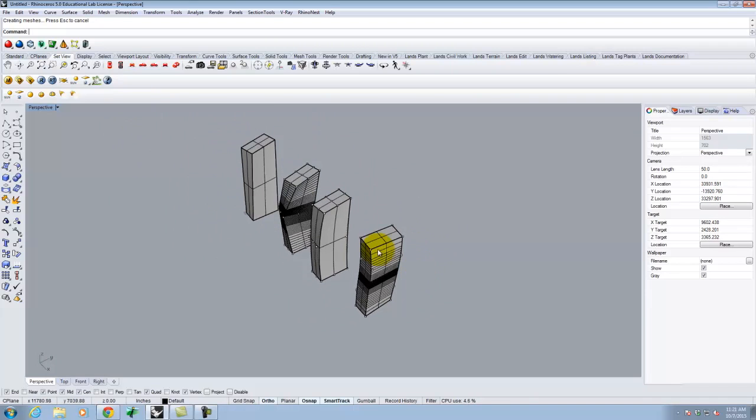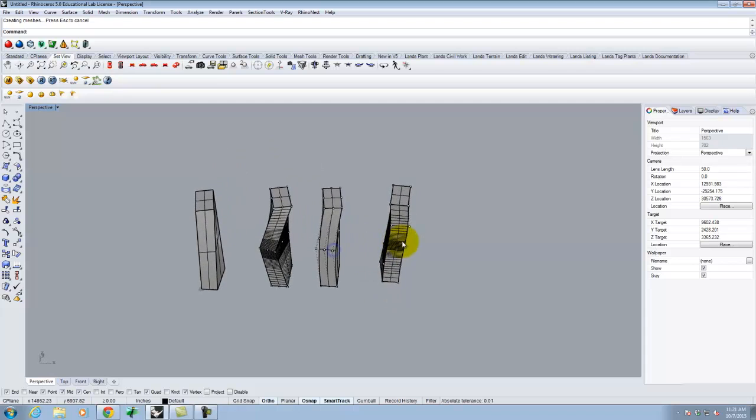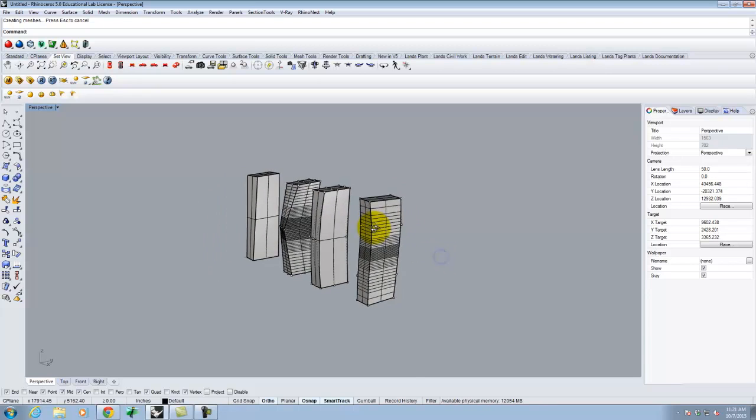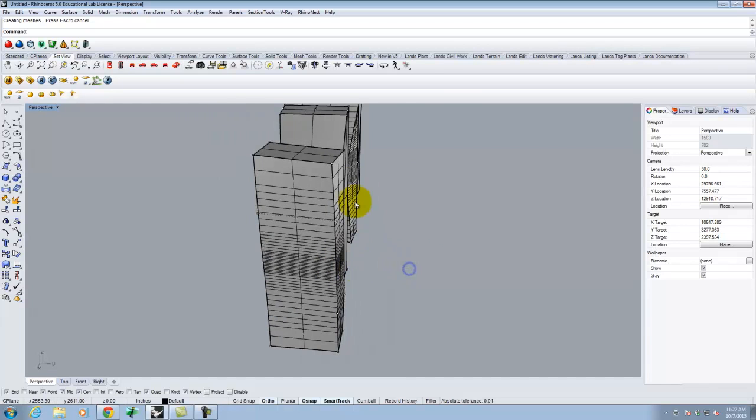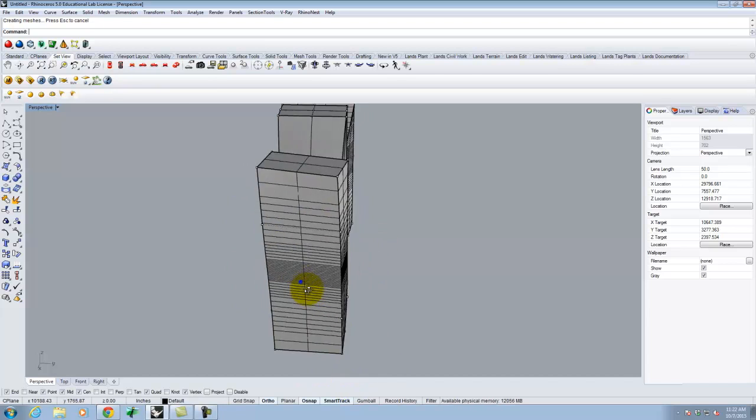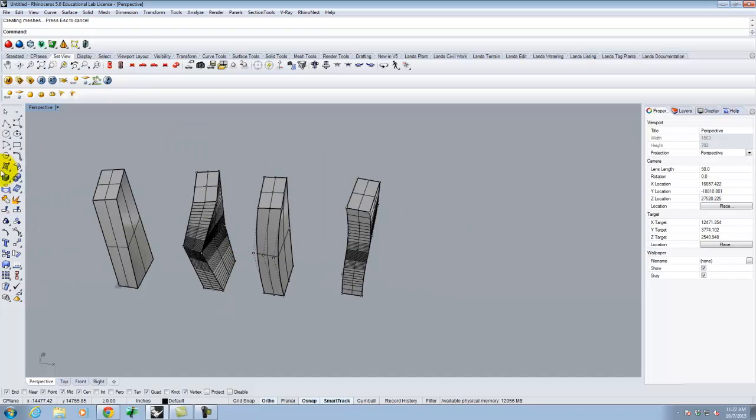I would stay away from the degree of 3 because it adds a layer of complex curvature that you really don't need at this point. These shapes that I've done so far today are all unrollable surfaces because they're a surface called a ruled surface, which basically means that there are two parallel lines, and when I connect them, there's always a straight line that connects them.